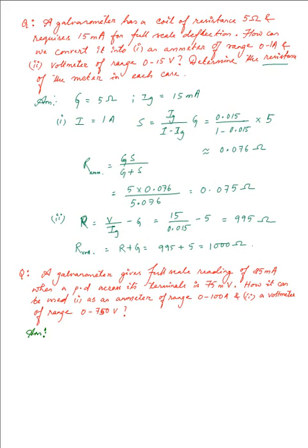So we wish to obtain the galvanometer resistance, and that will be equal to the voltage divided by the current. So G is going to be equal to the voltage which is 75 millivolts divided by 25 milliampere. We need not write the units though, but still it's 3 ohms. The millis get cancelled out, and the volt by ampere is going to give me ohms.